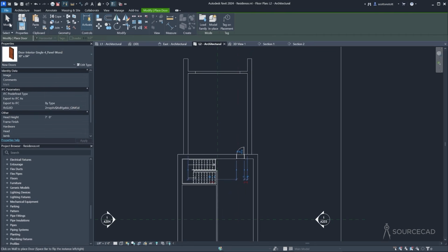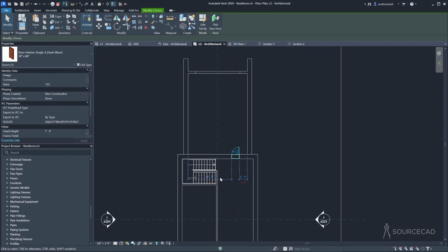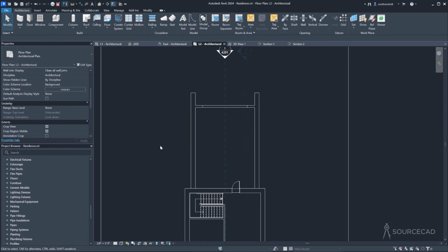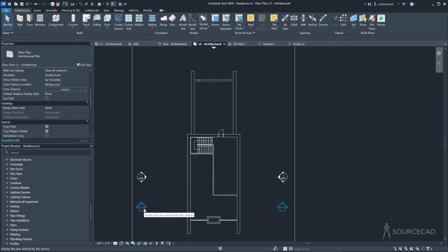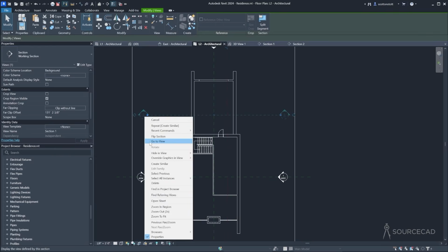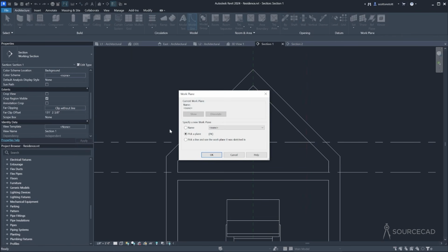that. Now, we have a space in here that we can detail, but first I'm going to maybe move the door over. We need to think about how much space do we really have in here, you know? It's going to be constrained because we have the roof cutting back. So I think this is where a section might be helpful. I want to look in this section here. I'm going to move this section up and then go to that view. And this will help me decide some things about heights and so on. So let's put in a model line here.